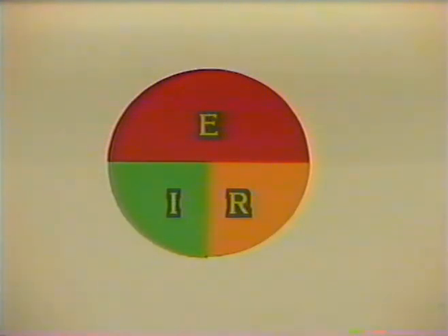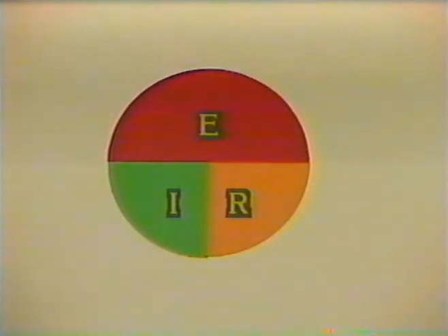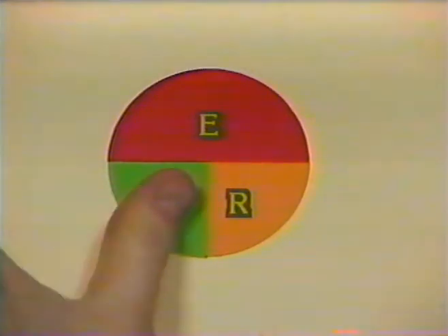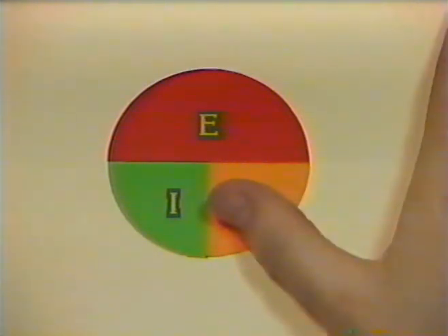Voltage on the top half of the circle is equal to the product of current multiplied by resistance on the bottom half of the circle. To find the value of current, divide the voltage by the resistance. To find the value of resistance, divide the voltage by the current.